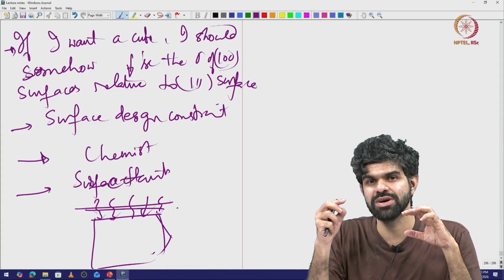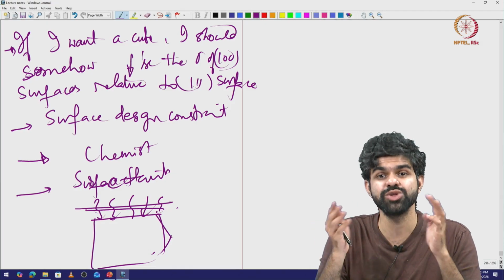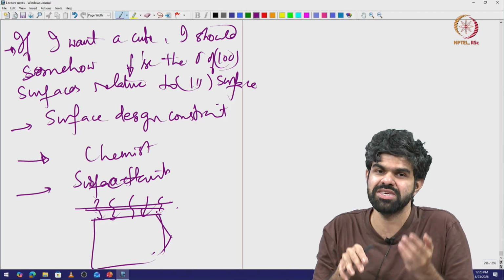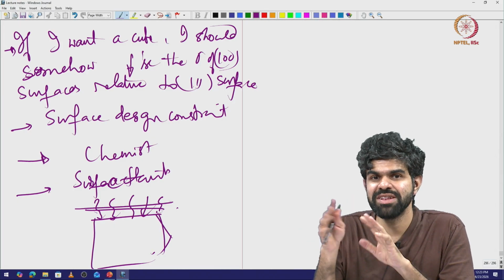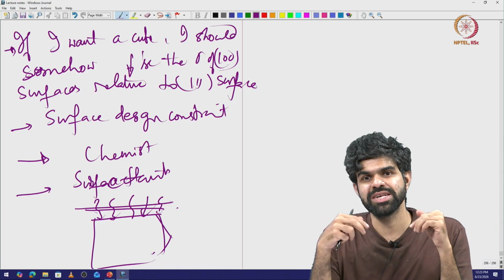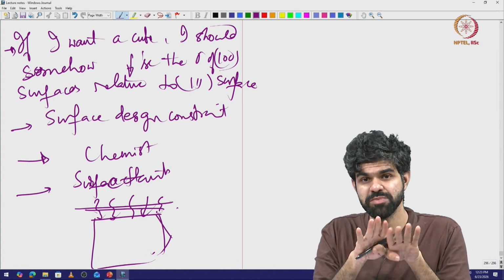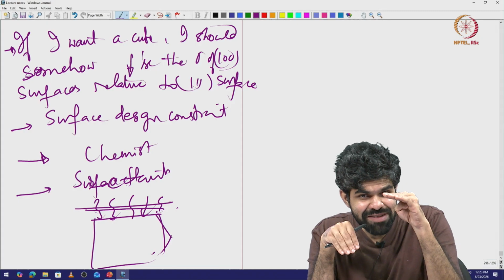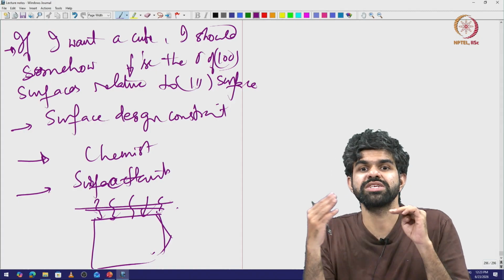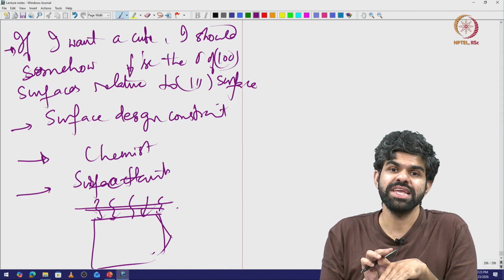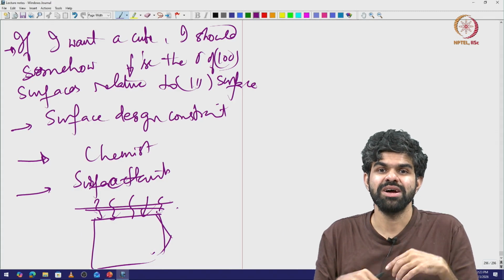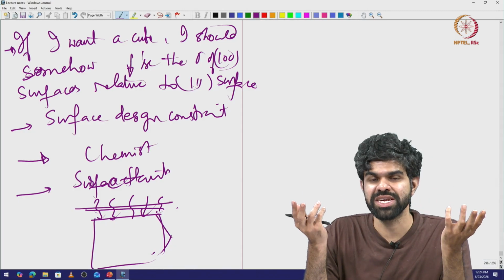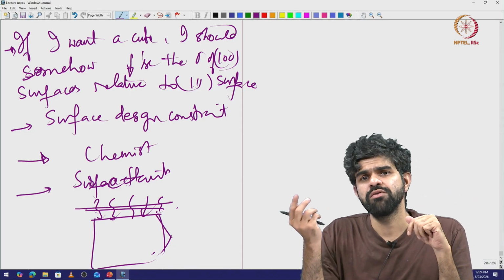So increasing the bonding potential reduces the surface energy, okay. So increasing the binding energy will reduce the surface energy. We'll have a small equation in the upcoming classes when I look at interfaces. From surfaces we go to interfaces. But yeah, I can selectively reduce the gamma of 100 with respect to 111, and then what I end up getting are these cubes of platinum and not really dodecahedra of platinum, okay. So I can do some shape engineering depending on what I really want, right.